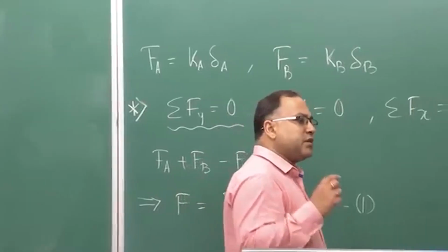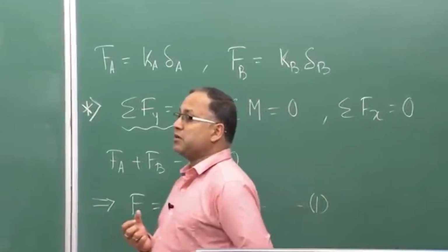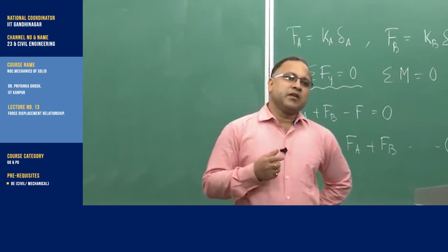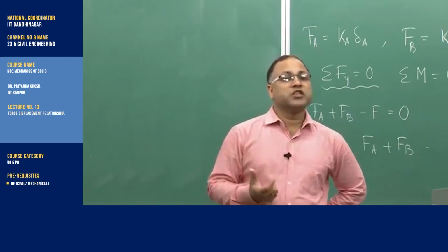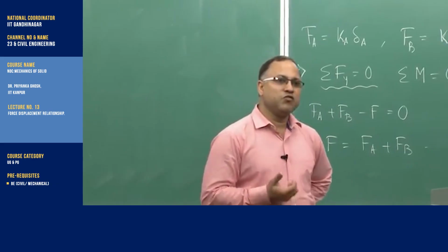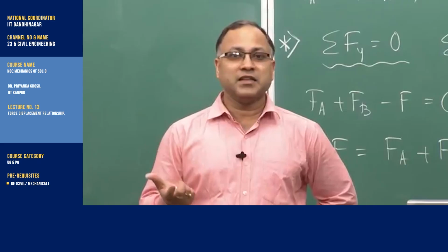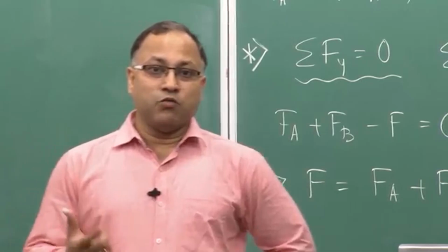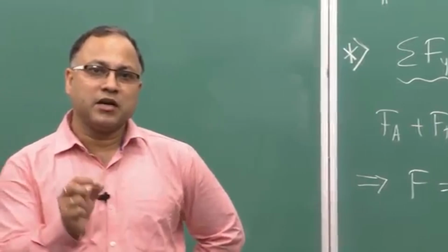The amount of displacement the piston is experiencing, and if I am not considering any gap between the piston and the spring after the deformation, then whatever amount of displacement the piston experiences, the same amount of deformation will happen in the spring itself. In both the springs, whatever deformation happens will be equal to the displacement of the piston. That is nothing but your geometric compatibility, the geometric fit. That is the condition by which the system will be governed.